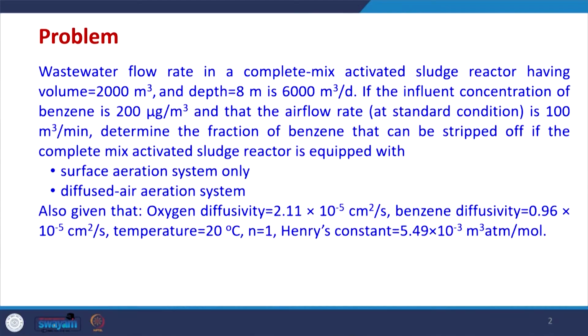In this particular problem, suppose the industry is telling us that they already have a reactor with a 2000 meter cube volume, and that the depth of the whole activated sludge process, or the aeration unit, is only 8 meter, and they have a flow rate of 6000 meter cube per day of water.